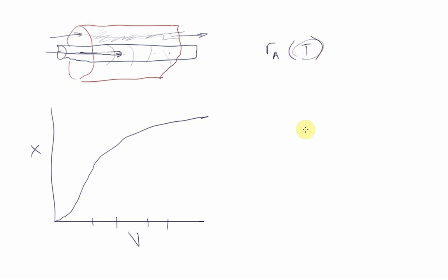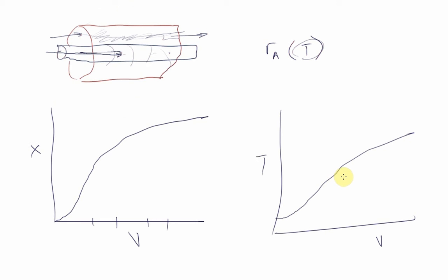So remember we said that there's a rule of thumb that's crept into this field, which is for a 10-degree rise in temperature, the reaction rate can double. So if you imagine this case where, let's say, we've got two temperature profiles, and let's say we make a 10-degree error in our calculation, then the conversion that we might get for this curve might do something like this, whereas the conversion we get in the other graph might do something like that.